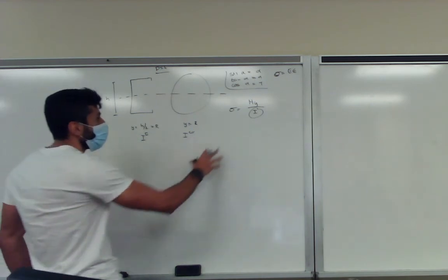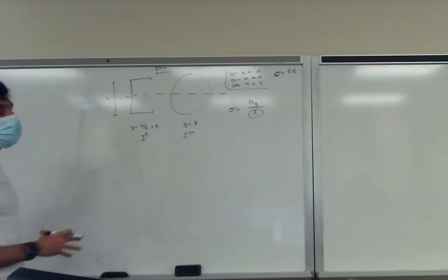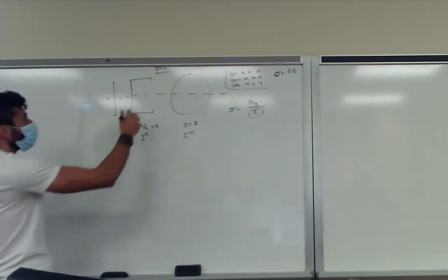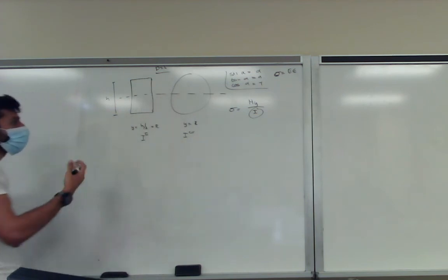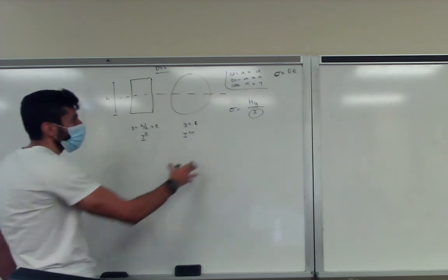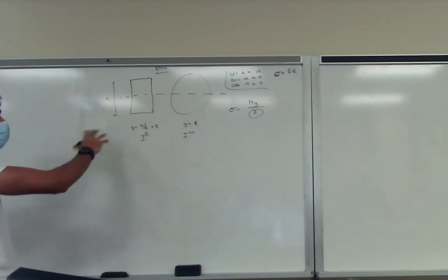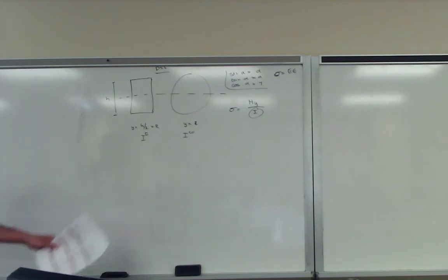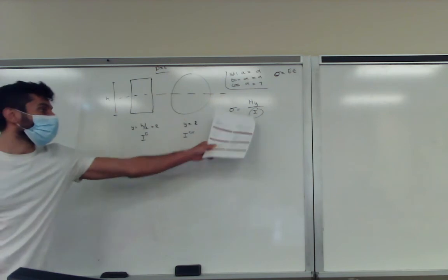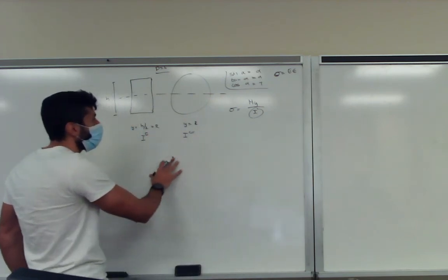And then, of course, say for example in a fuselage, a circular cross section is always better, even compared to a closed one. So in some cases, you will still get failure, while another cross section might not give you failure. But the circular section will give you other advantages. So you want to increase this moment of inertia. And that's what we said earlier.